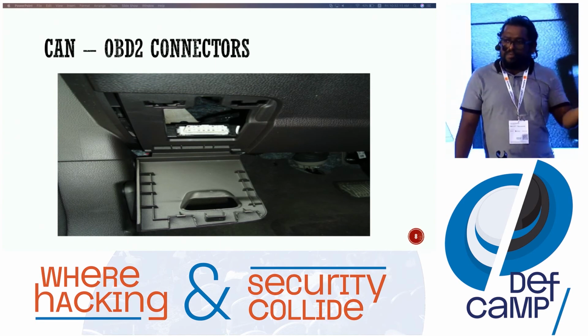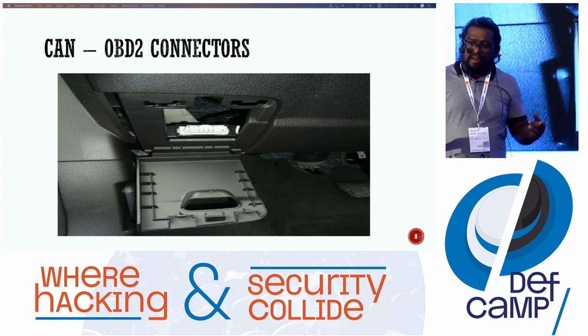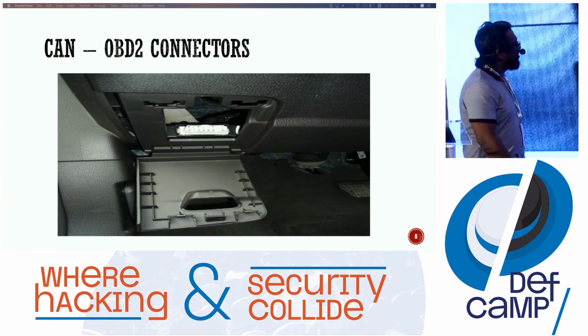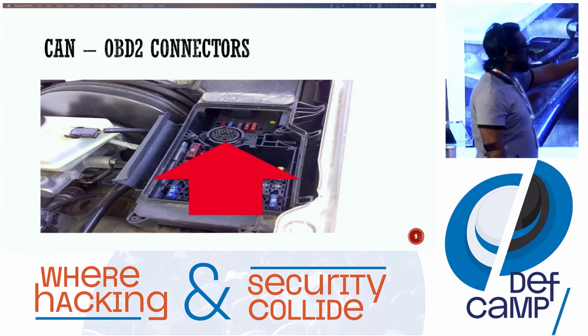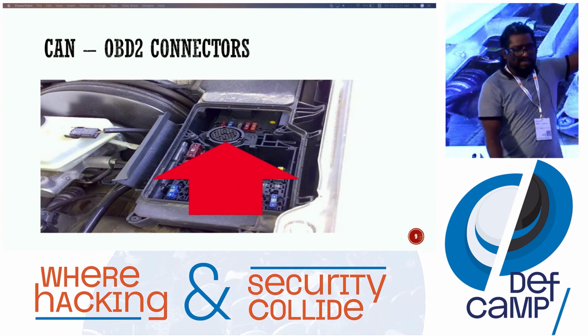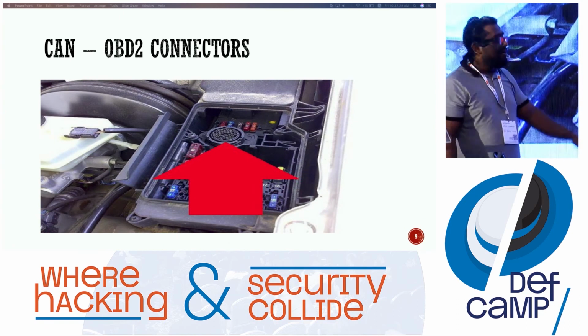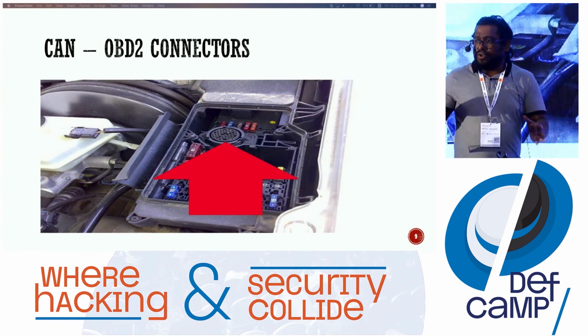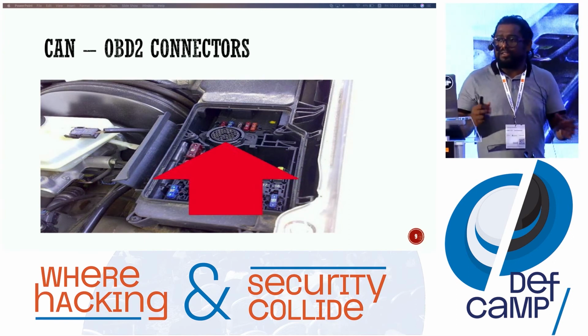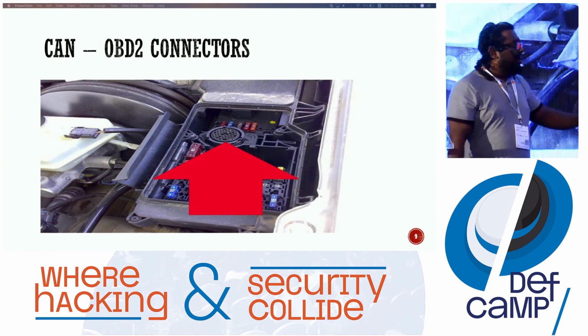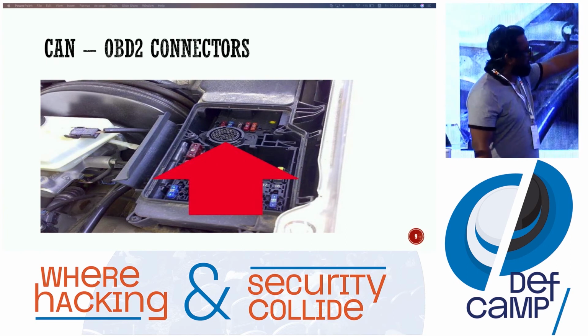Sometimes you come up with a female OBD2 or male OBD2 depending on the manufacturers. Sometimes you'll see those kinds of OBD2 as well. In that case, you need to have some sort of converter. If you talk about USB or other DB9 cables, you need to have a DB9 to OBD2 converter. In that case, you will have this specifically.